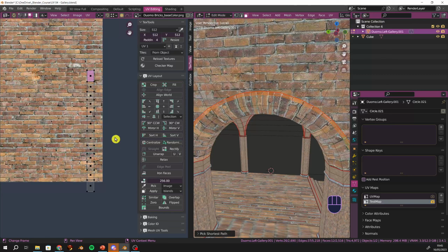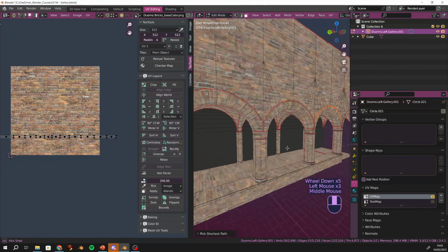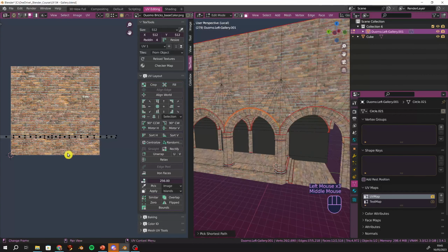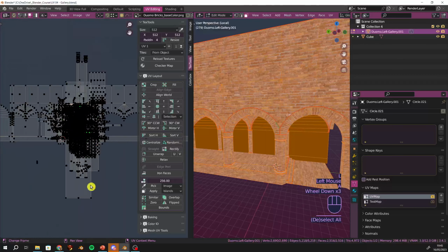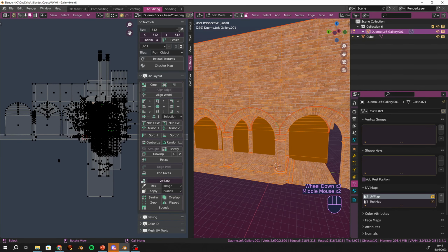I have a question, sorry. You're not baking this texture, are you? You're just applying it in Second Life once you've got the model in there. Is that correct? Right. When you look at this one, this looks good. But if I look at the UV map, it looks like this. No way you can bake this, yeah. That's why I'm asking. Exactly. This will show the texture like this because Second Life doesn't really care in this case. It will just scale the textures according to this UV map, but it's not baked.